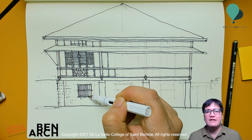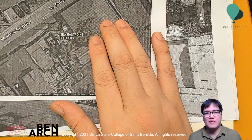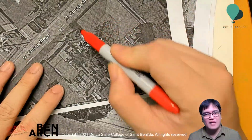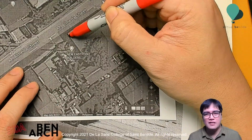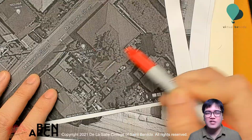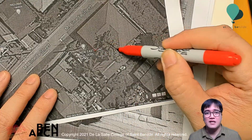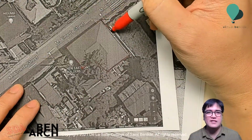But let's go more in depth with the steps. So one, the Google Maps reference is normally scaled more or less, so I could trust it. Now, what I do is I switch to satellite view and zoom in as much as possible to the target building, so now you can see the top view, and normally you can see the provided scale bar.